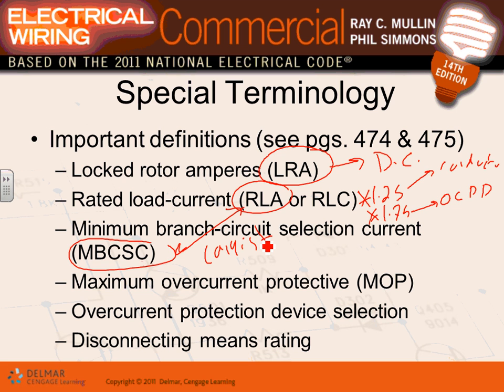They actually go further than that. You know what they do, guys? Yesterday, Derek, remember when I told you minimum circuit ampacity for the conductors and maximum overcurrent protection device? They actually give you the maximum overcurrent protection device. So they did this calculation for you, and they give you the maximum overcurrent protection device is 50 amp. On the nameplate, they will tell you what type of fuse or circuit breaker and what size you are to install on this equipment, on the refrigeration equipment. So they call it the maximum overcurrent protection device. Like the chiller that we had, it says 110. You are to stick a 110. Remember that chiller condensing unit? We said 110. We stick a 110.